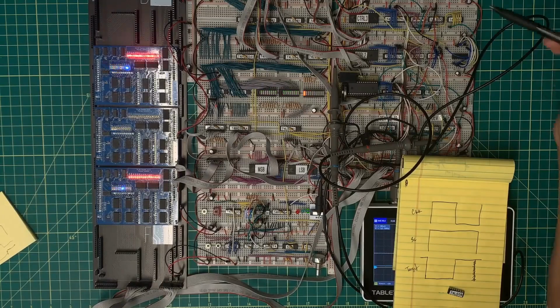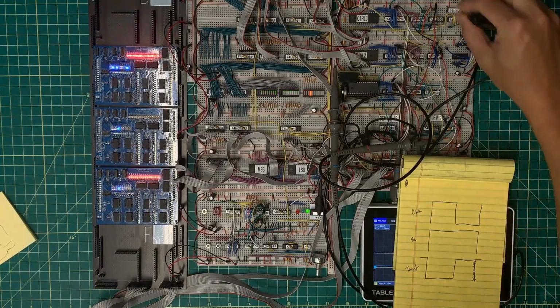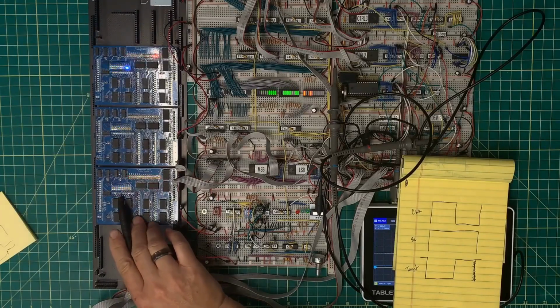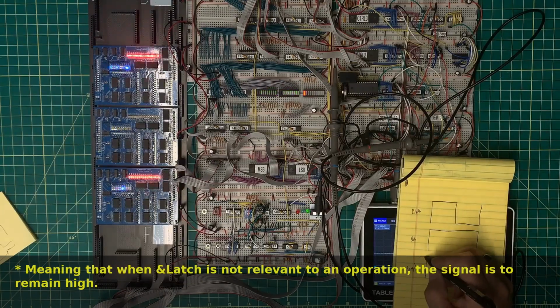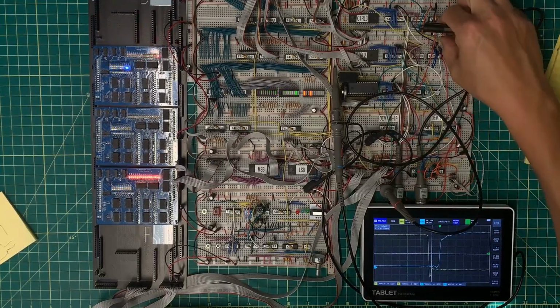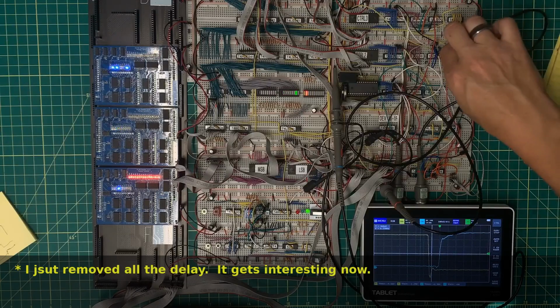Okay, I was totally prepared to rip out this NAND gate and make changes, but then I realized that my default or unused state wasn't going to be properly represented. And the LEDs here are set to come on when voltage is 0. And therefore, in order to maintain this, the NAND gate is really the proper tool for the job. All right, so now if I look at my signal again, what can I do about this delay?